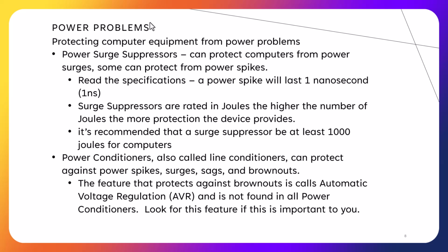So when it comes to power problems and how to protect against those, we're going to start with how to protect against our spikes and surges. The power surge suppressors can protect against surges and spikes. Read the specifications of the surge suppressors you're going to buy. Remember, a power spike will only last a nanosecond, so you want to make sure the surge suppressor can handle the short duration that the spike is going to hit in.